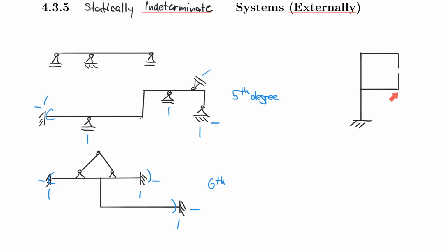And as of right now, this is a completely statically determinate system because everything is free to move and there's no restriction. But as soon as I come in and weld this together, so let's say I weld something on here and I rigidly connect this, I have a problem that engineers have to address, and that is that now this system here is connected rigidly, which transmits the forces from one part of the structure to another one.